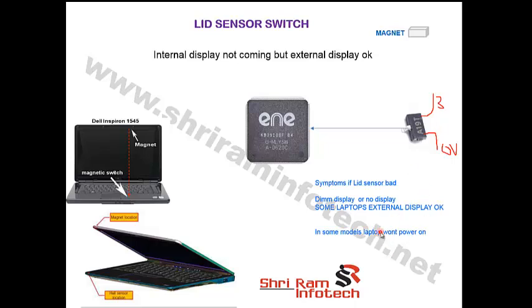Suppose you have a dead laptop, and you check all the 3 volt signals at the SIO, RSMRST, like the power button, you have checked, you flashed the BIOS, but still the laptop is not powering on. At that time you have to check the 3 volt at the lid sensor. If the 3 volt is not coming over there, then your laptop won't turn on. So you have to focus like that. So 3 problems will occur if this lid sensor is faulty. Okay.